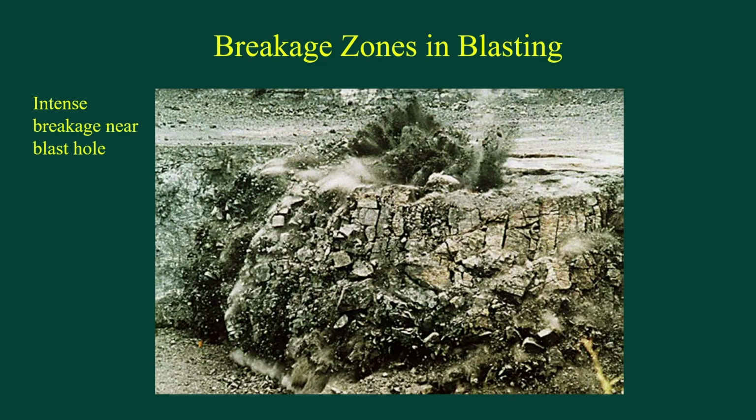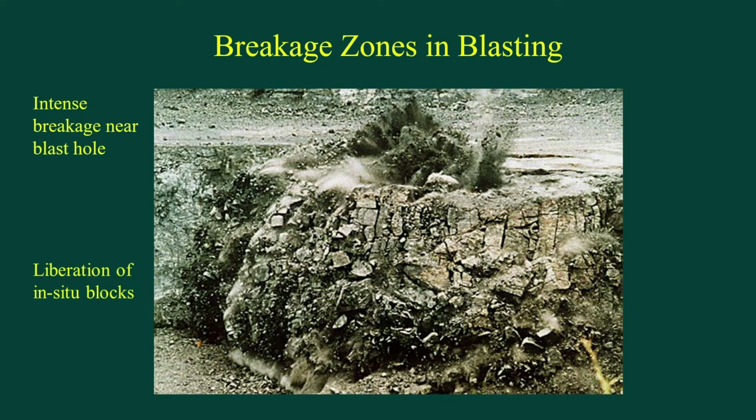So let's have a look at the breakage zones in blasting. Here we can see near to the blast hole some intense size reduction breakage taking place. And here, further away from the blast hole, we are effectively liberating these blocks. We call these in situ blocks. And we can also see here heave taking place, where the explosive is transporting the broken material out onto the floor.